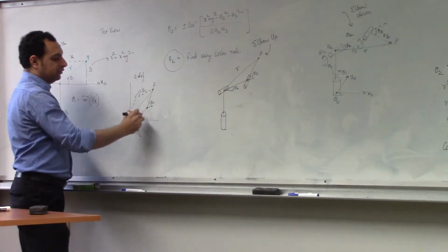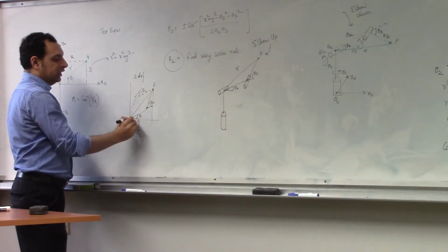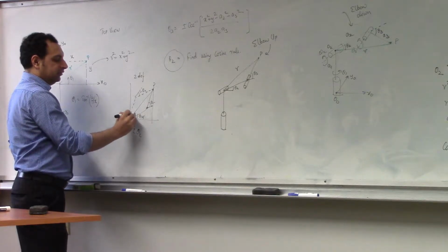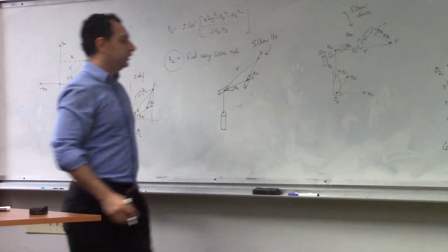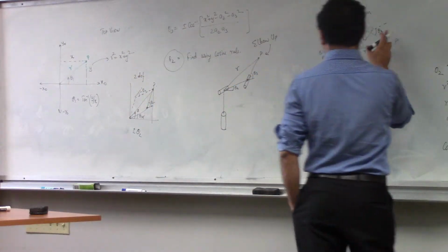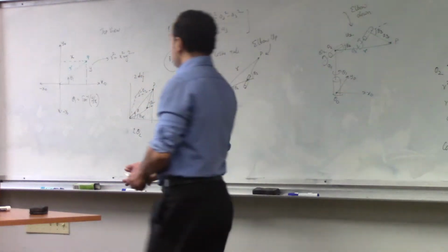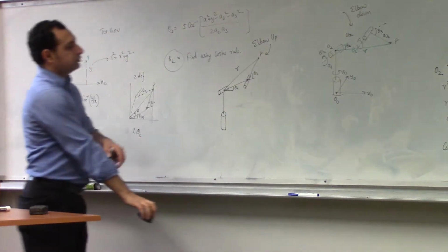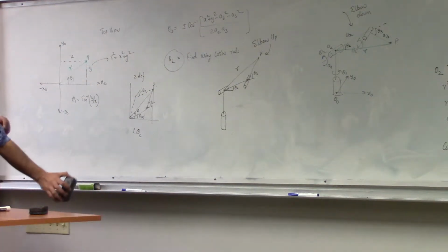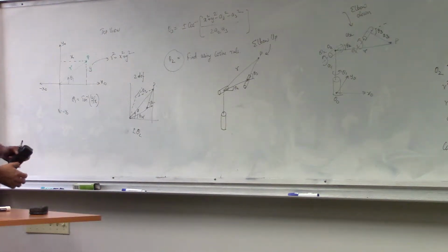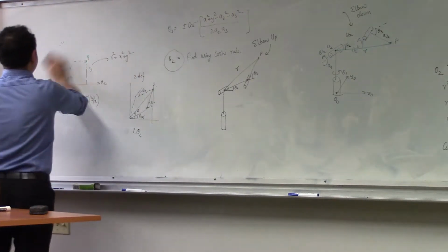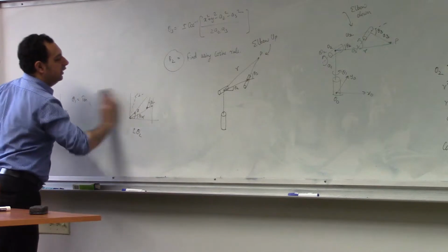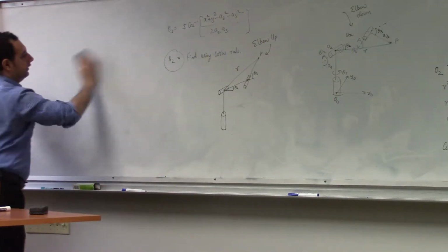You can first find out, like last time, what alpha is, find what beta is, and do it. Or you can find directly using the cosine rule, because you know a1, a2, and you can find theta 2 from there. All right, one thing that I have to tell you is a few special cases. I'm sorry, let's do that first, and then we'll continue.